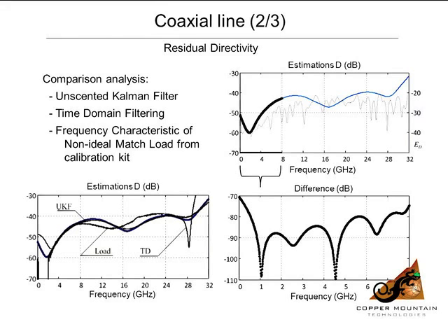Obviously, a windowing function is chosen to select the time domain or the time response portion of interest and to reject the others. The other reflections can be considered to be interference to the reflection of interest. But regardless of what window function is chosen, you still see some distortion at the edges due to the window effect, the Gibbs effect.